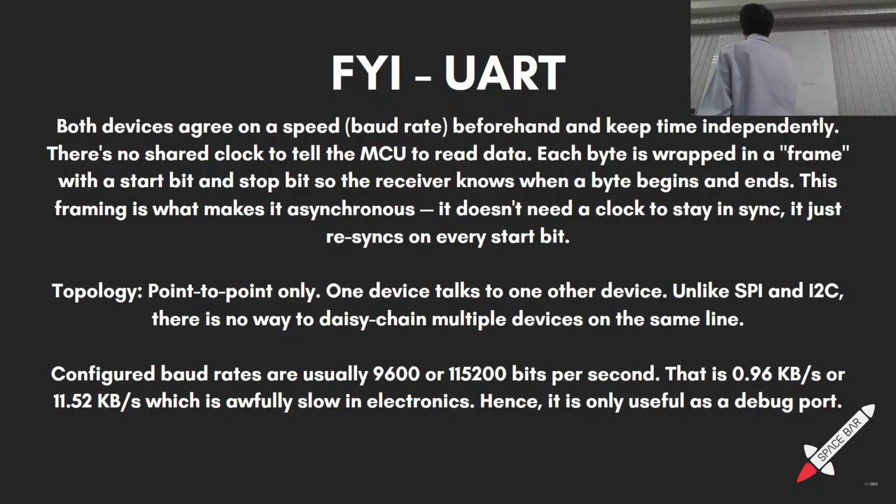So the clock is the reason why you do not need to provide a baud rate for I2C. Every time the clock goes high, everyone is like, oh, data is coming. Data is ready when the clock goes high or goes low depending on the implementation, but we don't care about that. And the data is determined by the clock.